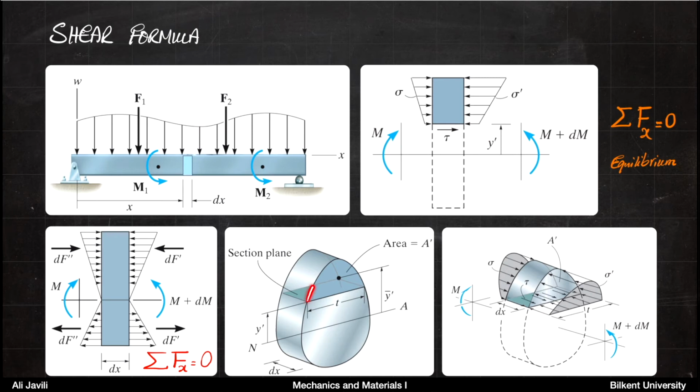So basically on this upper portion, you would have normal stresses acting, which are shown here. But also at that bottom surface, there would be shear stresses. And that shear stress, if you look at it, is exactly the longitudinal shear stress we talked about.